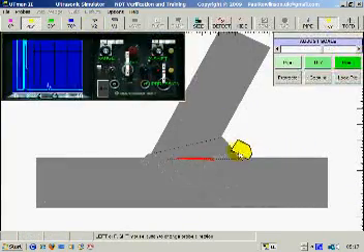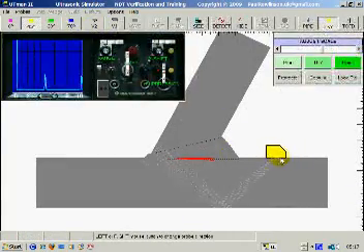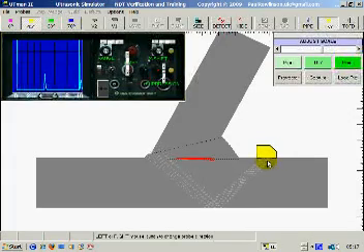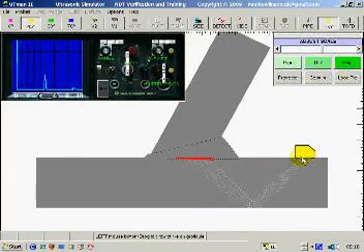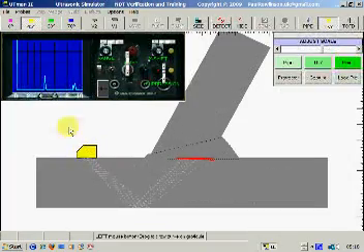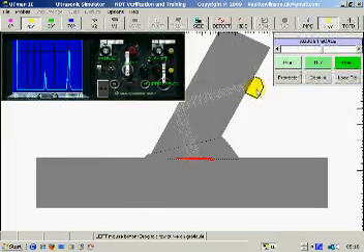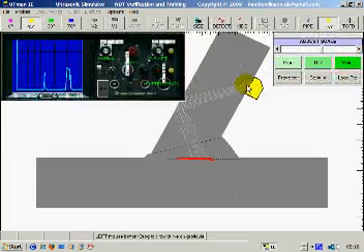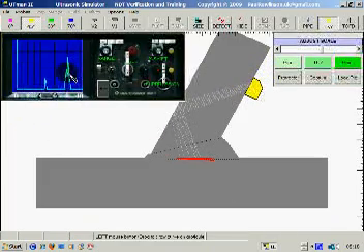So now, that defect, that echo there, here is representing this internal surface of this TKY joint. The first echo is the back wall. The defect, not a good response. In fact, the response is this one here. That's better, we can see this one. That's a good response here.